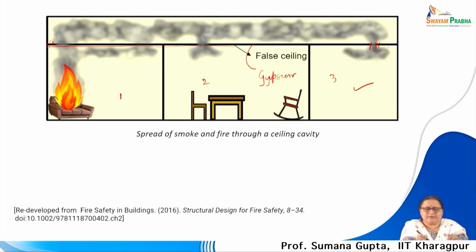So, the main point is, if I could have had some barrier here, as I had talked about for the AC, there could have been some dampers here that could have automatically closed and stopped the smoke movement from here to the other. Now, this is a case where compartments are made within a room. It is very difficult to provide such dampers, and it is usually overlooked or not provided, but a safer design would be to provide such dampers over here also.